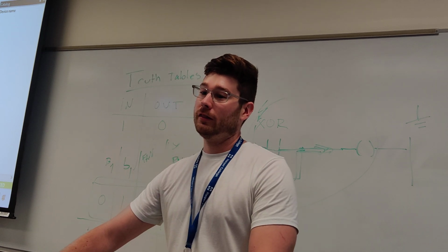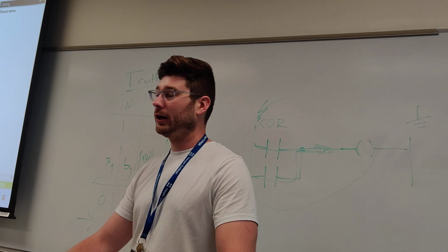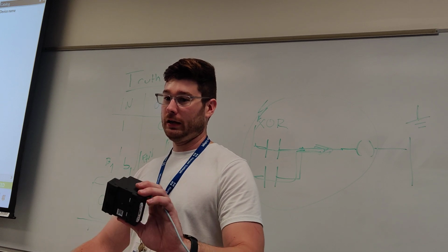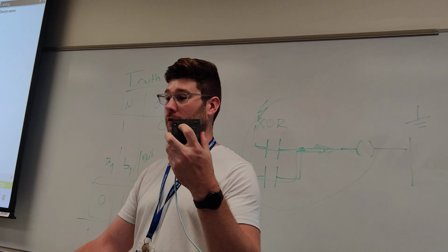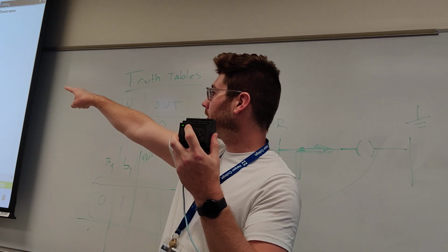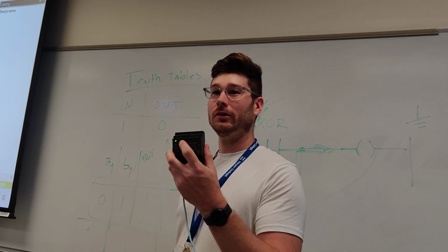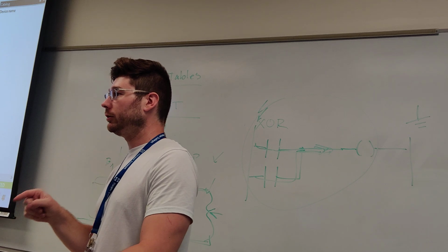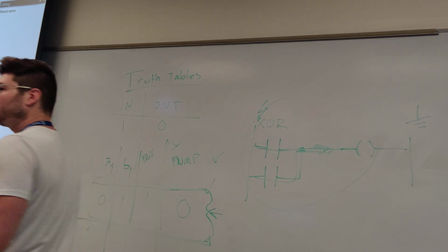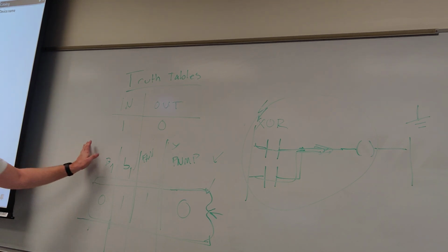Nice. Okay, so this is the power of live debug mode. When I press this button and I have just attached or programmed this device, you can see it light up on this network. You see how it's like I'm bridging it or I'm turning on that button. As you are evaluating whether this program does what you think it should do, you will actually be able to see the ones and zeros turn on in your ladder, in your rung. And then you can compare it to your truth table.